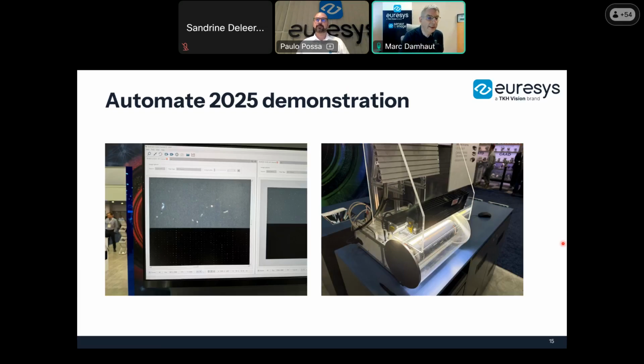So we end up on the top of the image here with the bright field illuminated image, and at the bottom of the window, the dark field illuminated image. This is all done by the frame grabber during the acquisition, using what we call DMA de-Interlacing or DMA de-Interleaving.